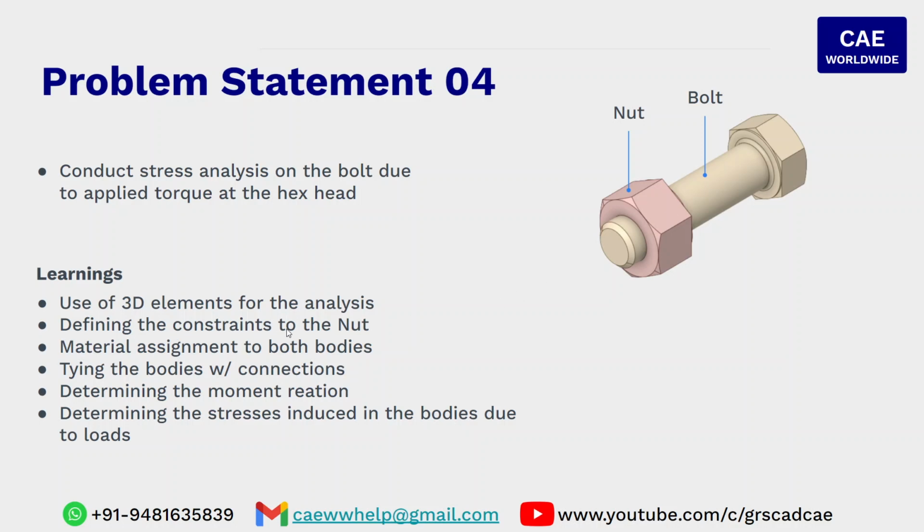Defining the constraints on the nut and material assignment to both the bodies. Tying the bodies with connections to replicate the bonded connection between them. Determining the moment reactions for the applied torque. And we also learn about determining the stresses induced in the bodies due to the loads.